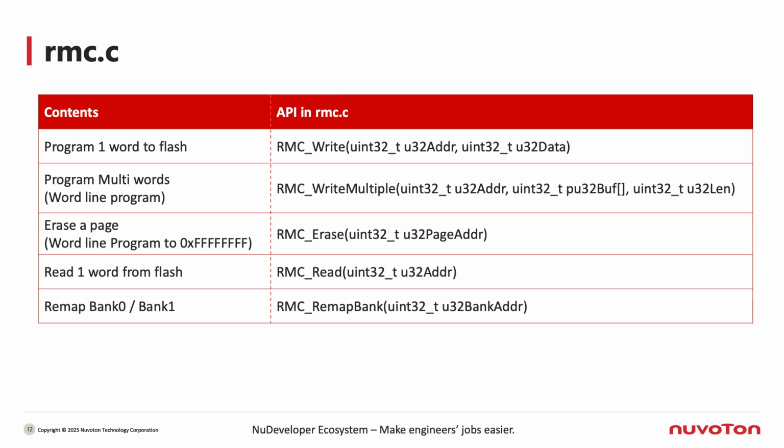This list shows some of the commonly used APIs. One point to note is that, to maintain consistency with other Nuvoton MCU series BSPs, the Erase a Page API here actually writes all bits to FF rather than performing a traditional erase.